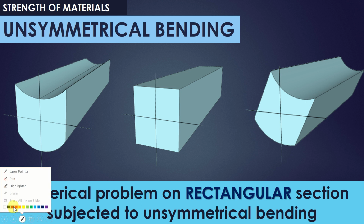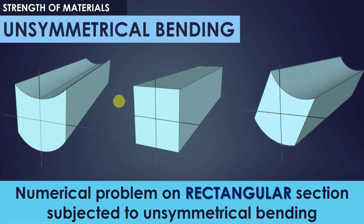So here let me talk about the rectangular section which is subjected to symmetrical bending. That means the load is acting along the centroidal axis. Let me say the centroidal axes are xx and yy, and imagine the load is W acting along y axis. So if you see the bending profile, that will be exactly like this, right? That is known as symmetrical bending.